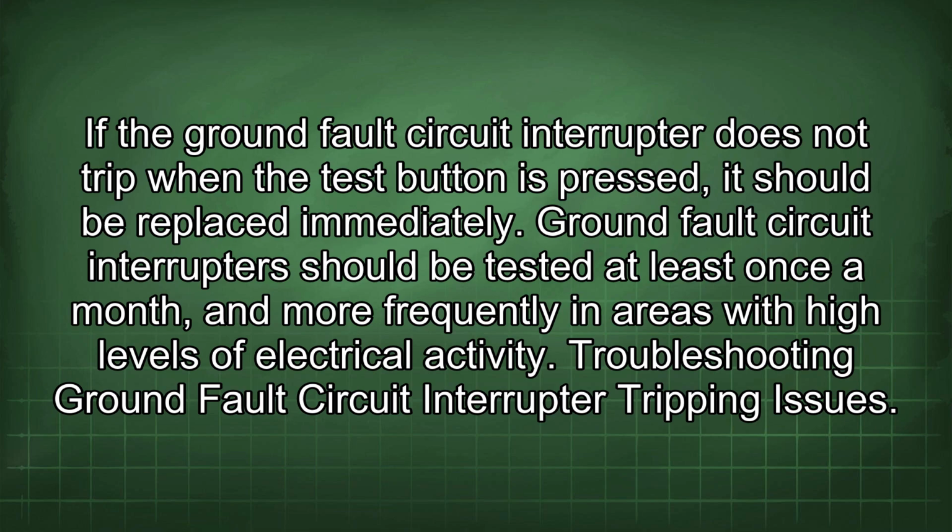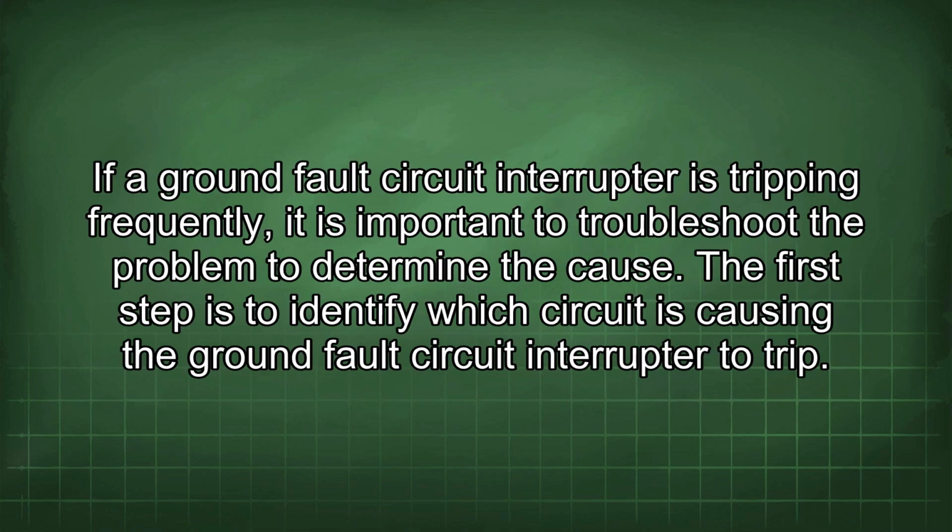Ground fault circuit interrupters should be tested at least once a month, and more frequently in areas with high levels of electrical activity. Troubleshooting ground fault circuit interrupter tripping issues. If a ground fault circuit interrupter is tripping frequently, it is important to troubleshoot the problem to determine the cause. The first step is to identify which circuit is causing the ground fault circuit interrupter to trip.